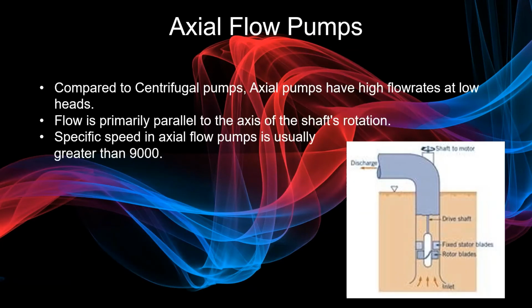We've talked a lot about centrifugal or radial flow pumps and their analysis. Now we're going to touch on axial flow pumps. Axial flow pumps are used for scenarios requiring high specific speeds and high flow rates at low heads, such as plumbing, drainage, and irrigation. Axial pumps are essentially a spinning propeller within a cylinder, and most of their flow is created by the tangential force of their spinning blades sucking up the fluid.